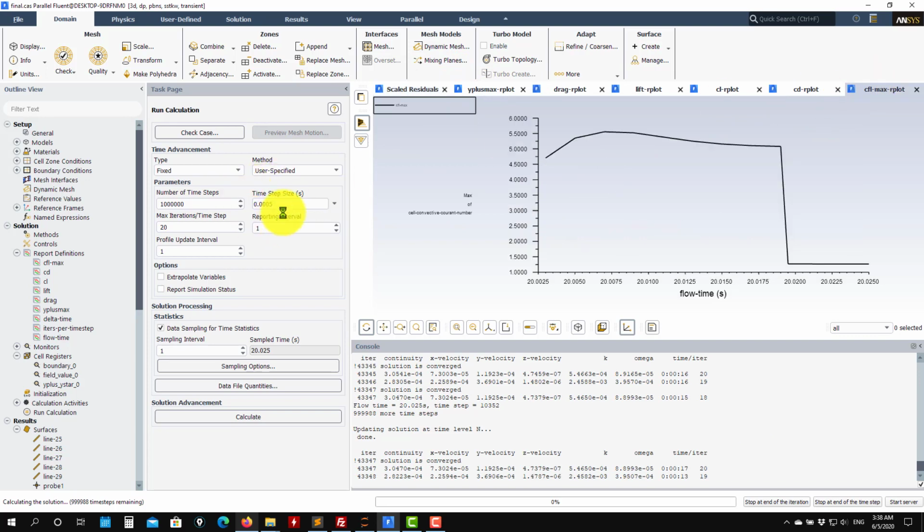But you make now the math that, see, previously using 10 to the minus 3, it was taking, let's say, 2 days. This one that you are halving will go to 4 days. And see that the increment in number of cells wasn't that much. It's just reducing the y plus value. So sometimes you also have to be careful in unsteady, because ideally we would like to always go wall resolving, but on unsteady that will have a price. So again, it will be a compromise.